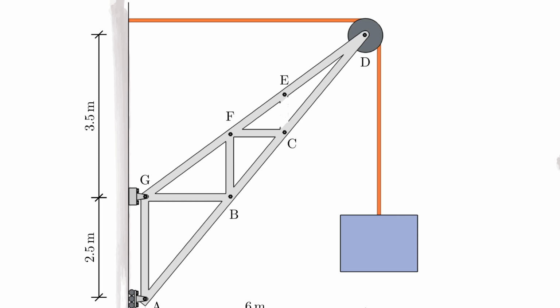And so now you see what's happening. It's actually such that now member CF is having the same condition. So now I have this structure here, these two parallel structural members are joined by a third one, and therefore I can erase that one as well. And so what I end up with is a structure that looks like this. And once again, now I have this condition at node F. I have 2 parallel members which are joined by a third one, and I can also erase that.